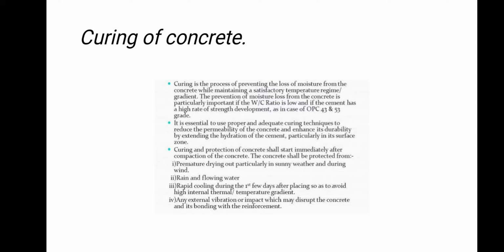It also helps with the heat of hydration, when heat is released from the reaction between cement and water. It is essential to use a proper and adequate curing technique to reduce the permeability of the concrete. The curing should be started immediately after the compaction of the concrete.